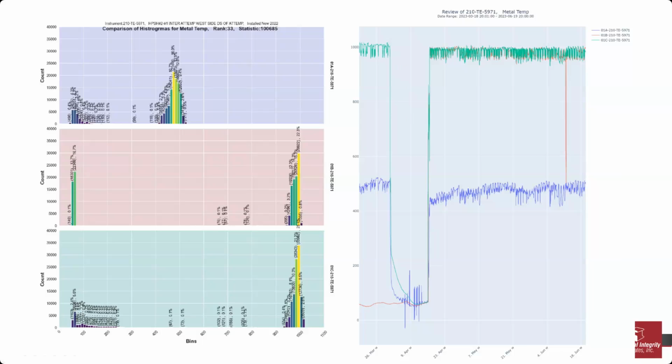So the one thing you quickly see is, this one tag, for example, the blue tag, is significantly different than the others. So this is a case where there are backup signals on these TCs, and we ended up switching this one to its backup signal because this one became unreliable. And after the switch, it basically jumped back up to here.